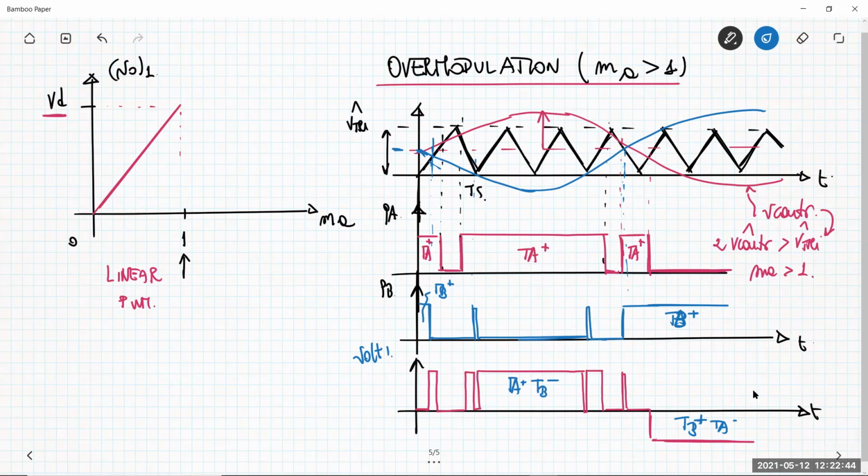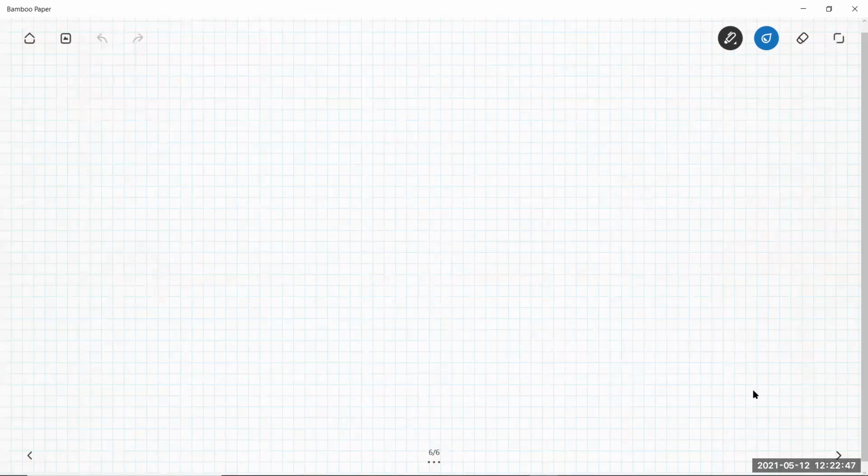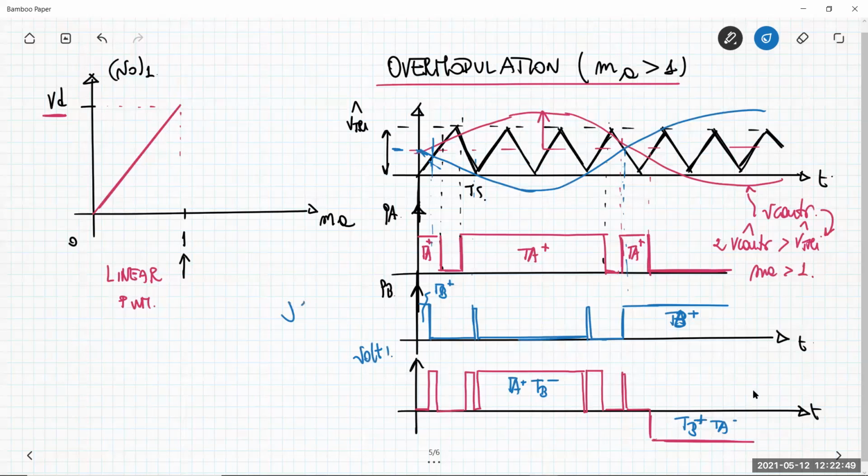Let me consider also what happens; this is for the unipolar modulation. So my discussion, nothing changed with respect to my previous results about unipolar pulse width modulation. I have only to think about the fact that there is a large portion of the control voltage which now comes from here, that is larger than the peak value, or lower than 0. So this has a direct impact on the output voltage. Okay, the output voltage is not exactly like before.